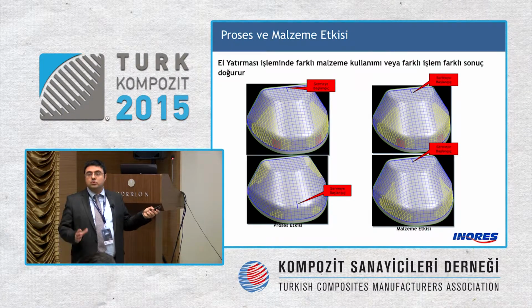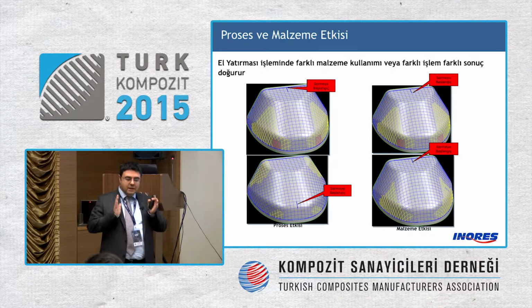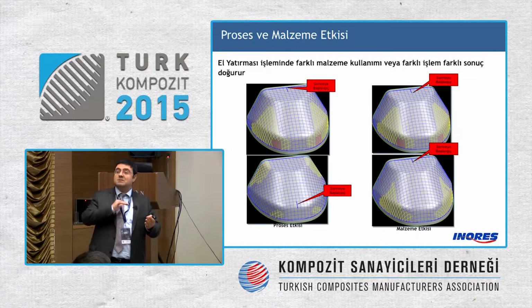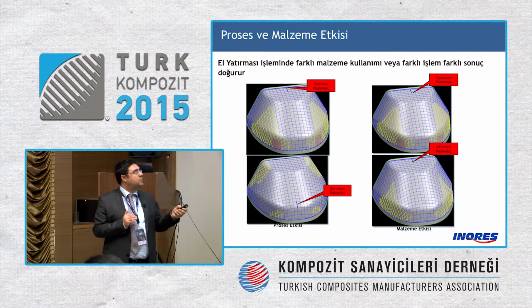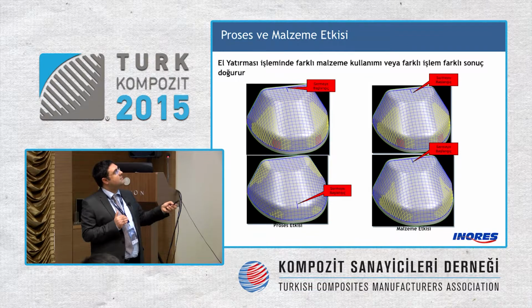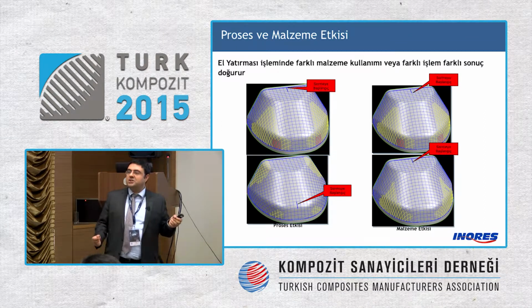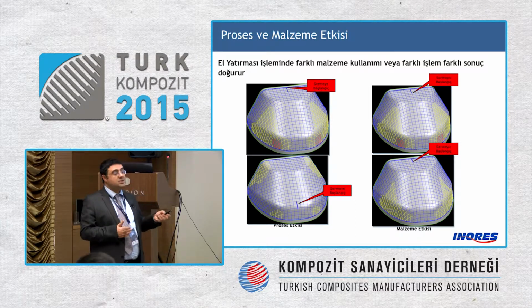Or if you change the material, although you have the same starting point, it might create a problem, because sometimes it is a combination of carbon with glass. Sometimes the composite ingredients are different. So here we start from the same point, and this is 45 degrees of lamination. The creasing might occur. But if you do it in another fashion, creasing might not occur. So it doesn't have to be just the same. With different materials, with different orientations, we might face different problems.